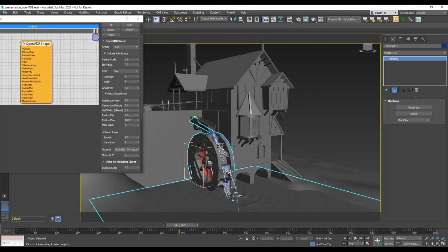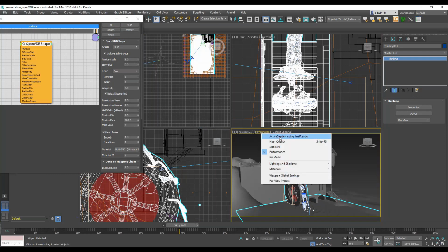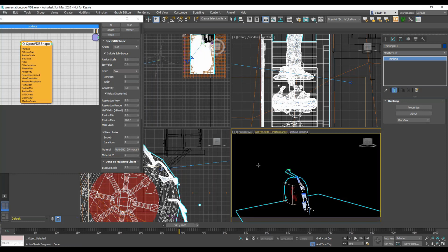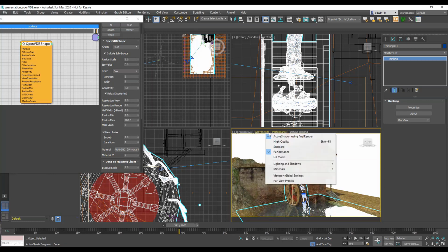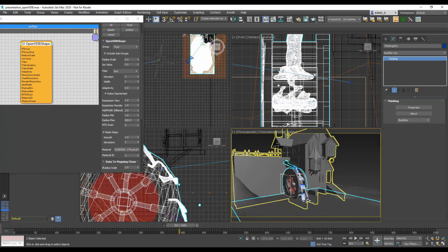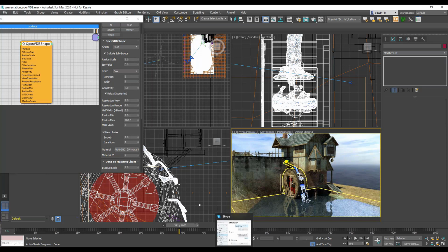And if we wanted to go really crazy, we can just use GPU ray tracing and go into the 3D Studio Max viewport and have GPU ray tracing here as well. Let me just go back into the physical camera because we have a physically accurate renderer, and then we can have physically accurate GPU rendering in here with everything, reflections, refractions, and just everything.